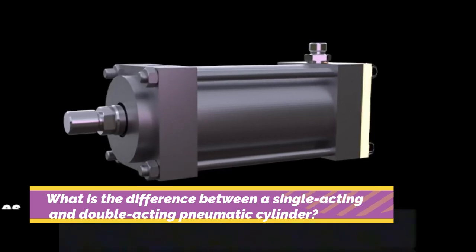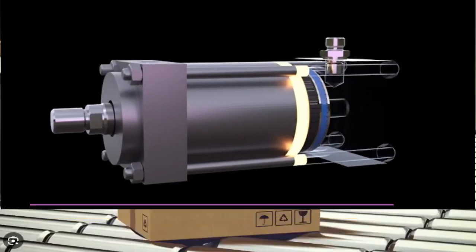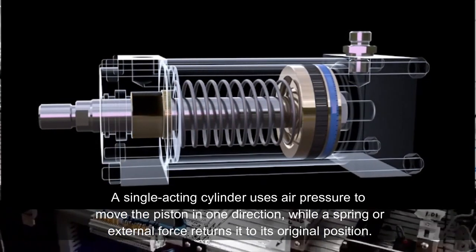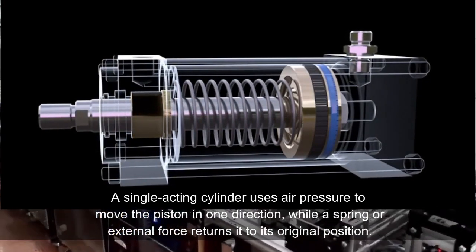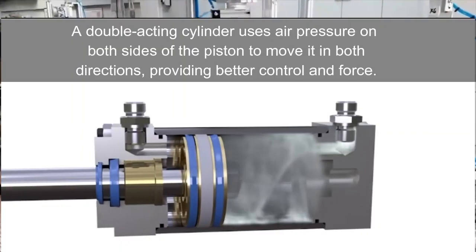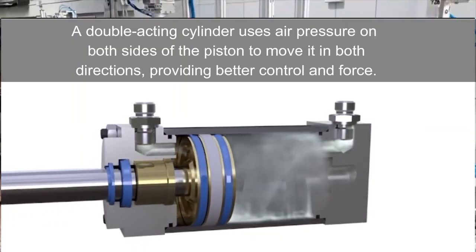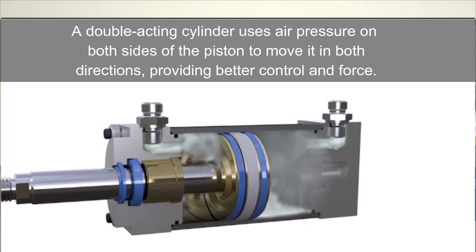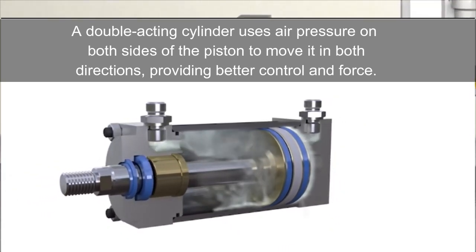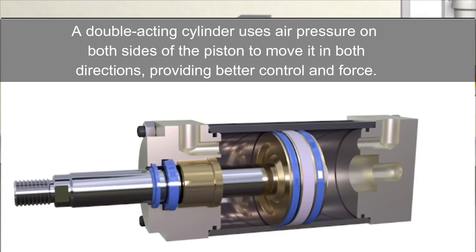What is the difference between a single-acting and a double-acting pneumatic cylinder? A single-acting cylinder uses air pressure to move the piston in one direction, while a spring or external force returns it to its original position. A double-acting cylinder uses air pressure on both sides of the piston to move it in both directions, providing better control and force.